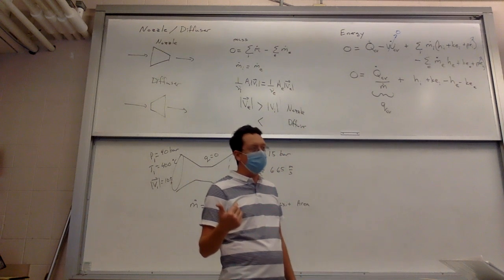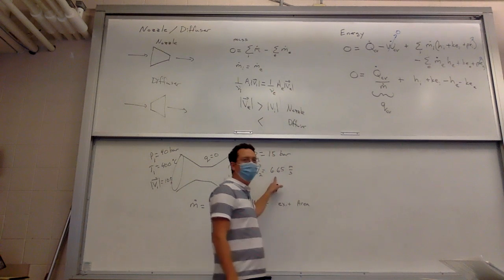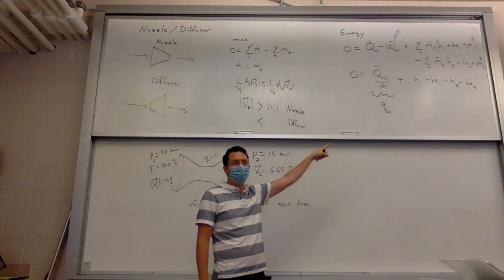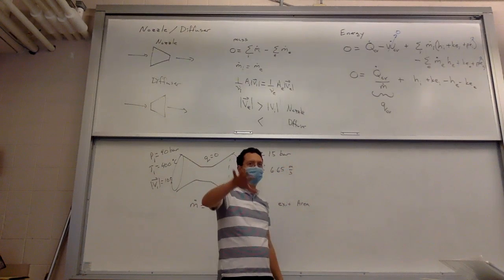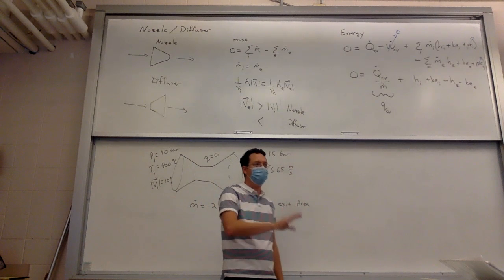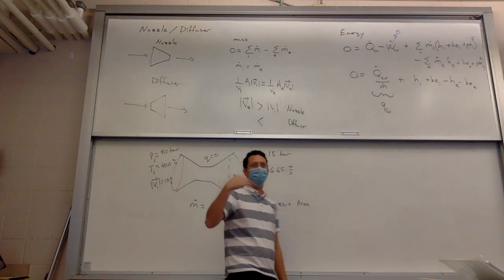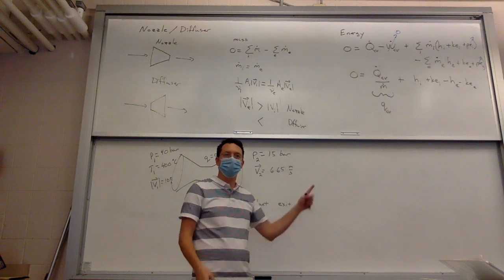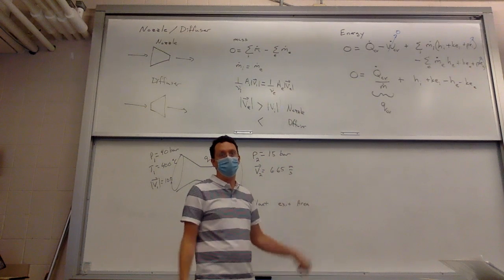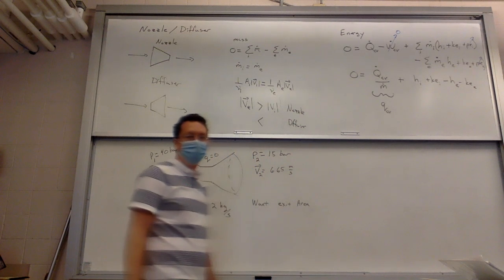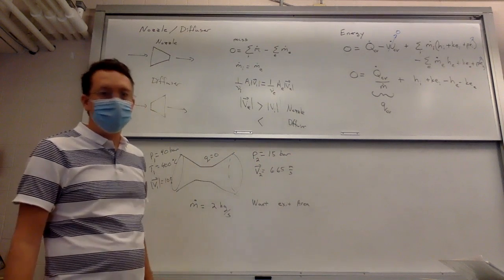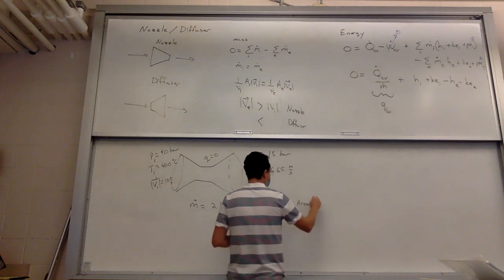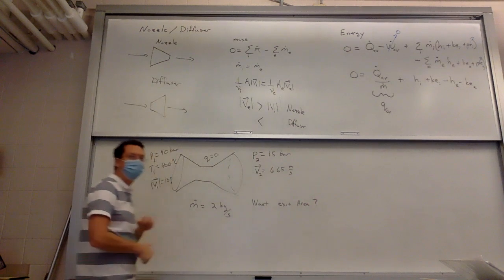If you're writing a problem, why would you crank up the velocity? Well, it means you probably don't want to ignore the kinetic energy terms. If you're talking about a lazy river, drop it. It doesn't matter. Everyday velocities are like 1 part in 1,000 in terms of the contribution. But at high speeds, all of a sudden, it's significant. All right. We want the exit area. That's what we have to do.